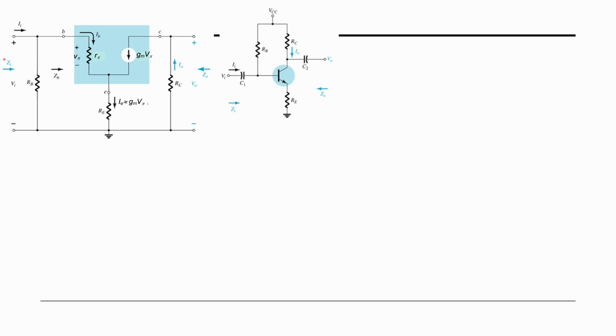You're going to have two impedances now: the input impedance and the impedance at the base, which is right before it goes into the base, after the base resistor. Then we have R pi, and then we have RE here, the resistor at the emitter side. And what else do we have here? We have gm V pi, and then we have RC.